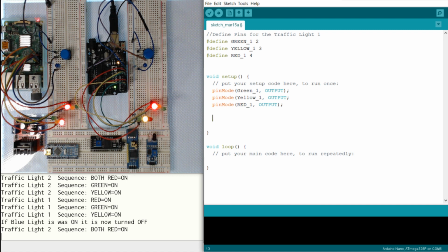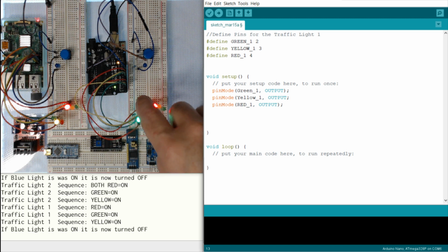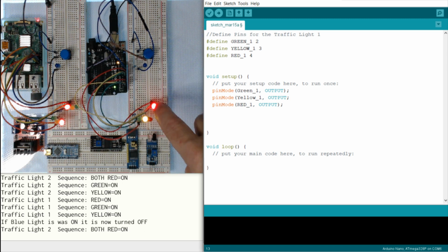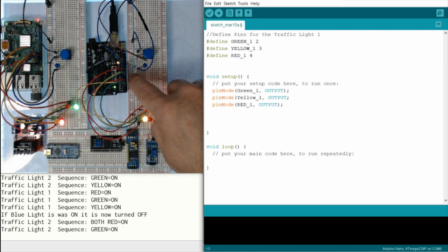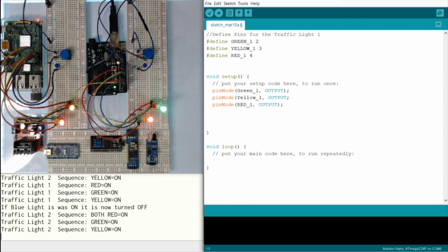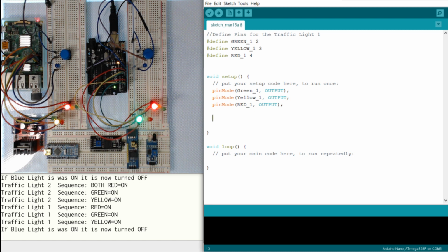And the way I have set this up, I use an inverted mode, which means the LED is connected to the positive side, the positive rail, and then the pin is connected to ground. The way I'm doing this is to draw as little current from the Arduino as possible. Otherwise the Arduino will provide current, and now it receives current.